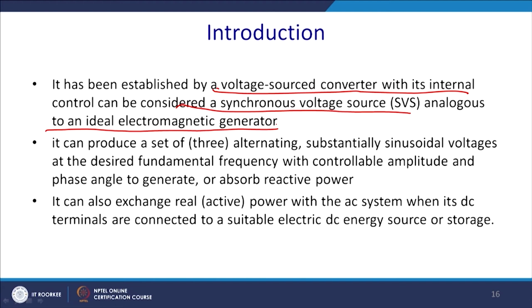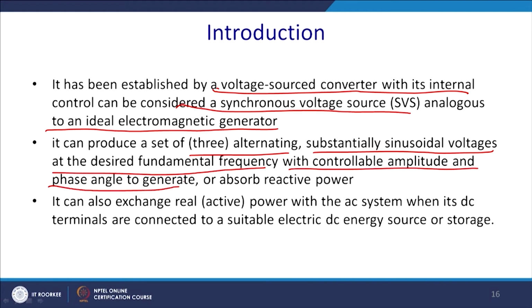It can produce a set of 3 alternating sinusoidal voltages at the desired fundamental frequency with controlled amplitude and phase angle, and generate or absorb real or reactive power. Generally, it is made for absorption of reactive power. Real power is automatically consumed to meet the losses.